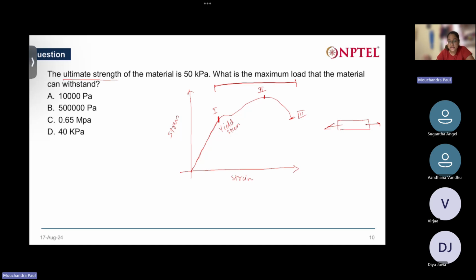Okay. So I'll answer for you. This point 3 represents the point in the experiment when the material underwent fracture. Means the material broke in two pieces. That is why stress and strain values cannot be recorded anymore. Whereas point 2 represents the highest point in the curve, or the highest value of stress that the material could sustain or resist before it underwent fracture.